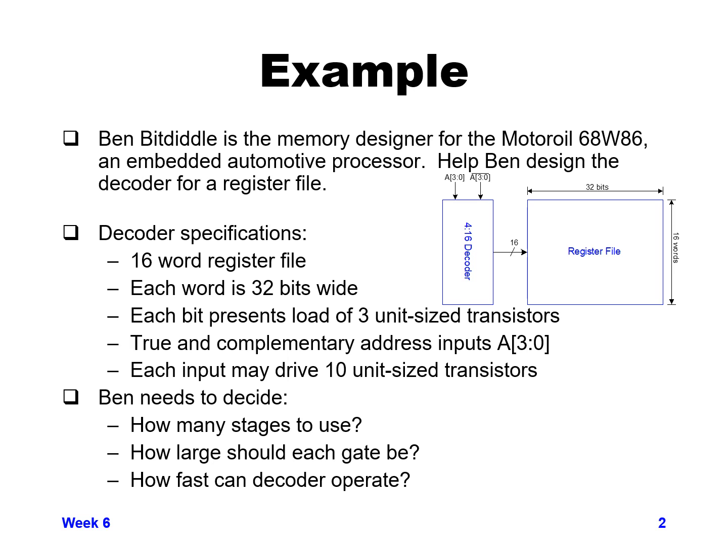And each bit represents a load of 32 unit size transistors. That would be equivalent, as I said a couple foils ago, the minimum size inverter would be a size 2 PMOS and a size 1 NMOS, so unit size 3. So each bit represents a load of one minimum size transistor or inverter, for example.